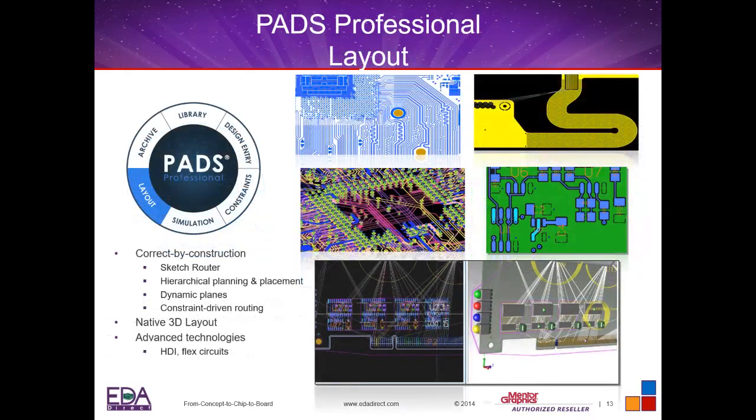You will have full layout abilities with the PADS Professional tools. You'll have sketch router, which is really powerful. Hierarchical planning and placements to help you with your placements of your designs. Dynamic planes that you can route through, kind of a WYSIWYG. And everything is constraint driven when you're doing your routing. So you've got full constraints that you can turn on. You've also got some advanced technologies, HDI and flex circuits, and we'll get into that a little bit here at the end of the webinar. But you've also got 3D layout that you can do part placement with as well.